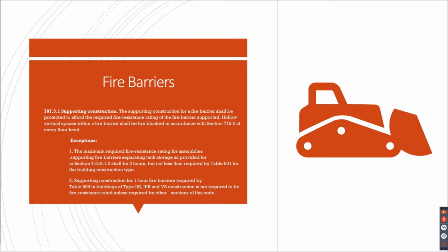And during construction, it was found that this 2-hour separation on the second floor wasn't supported with 2-hour supporting construction underneath, because the building element for that construction type only required that floor to be 1 hour. So make sure to look at all the pieces.